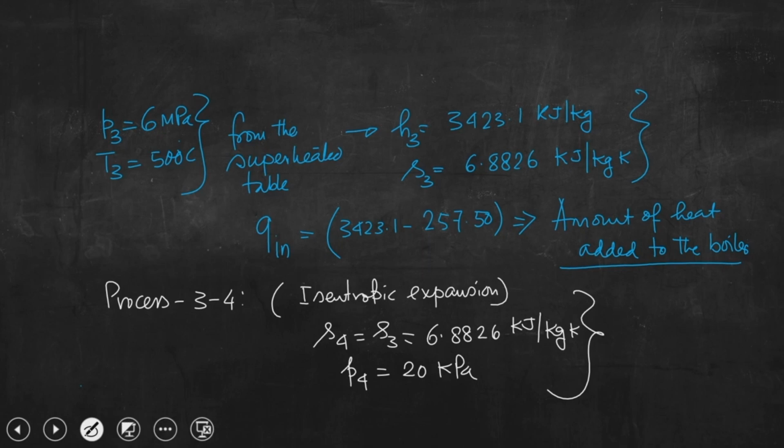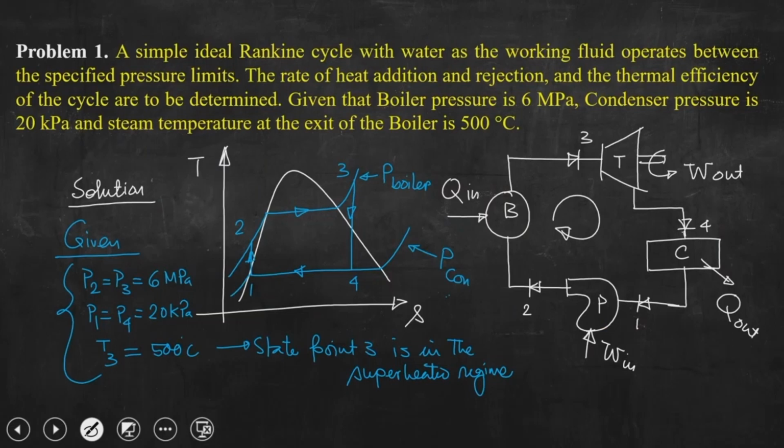Again this is something we need to understand. If we go to the TS diagram, the state point 4 is inside the vapor dome. So, the quality of point 4 is neither pure liquid nor pure vapor, right. It is a two phase mixture. Point 4 is not lying on the saturated vapor line, nor on the saturated liquid line, rather it is inside the vapor dome.